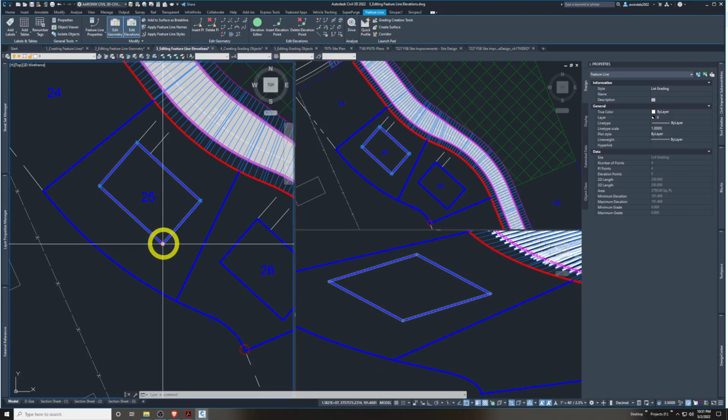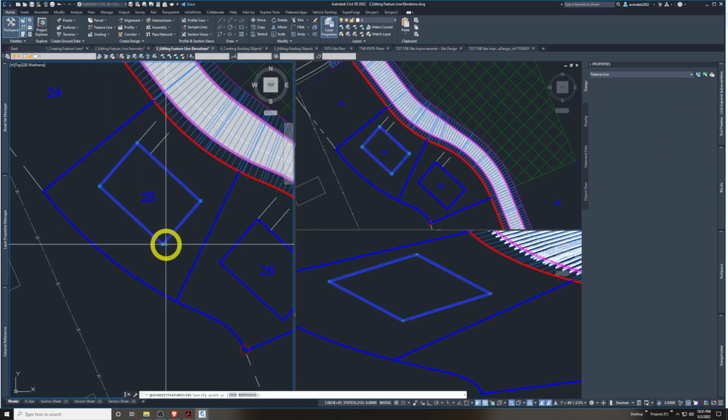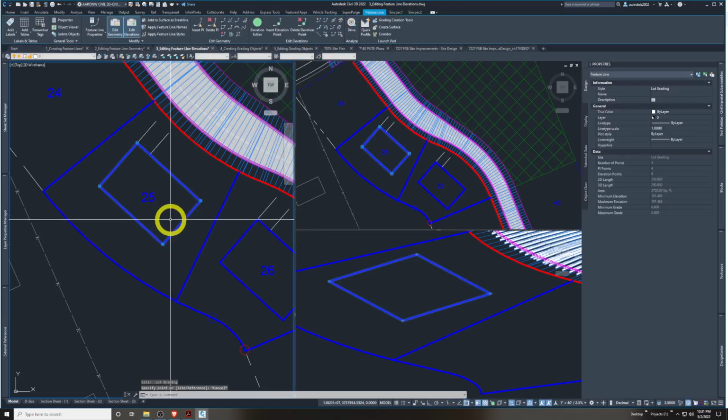If we hover on some of these, if we use our quick elevation edit, we can see it edited them relatively to each other. They're all elevation 0. So this raised them basically 2% from here to here. Using this as the reference, relative elevation, and then this is the set point, the grade to make it. And it got all 4 points. As you can see, the same elevation. So that's pretty cool, but a more advanced tool for sure.